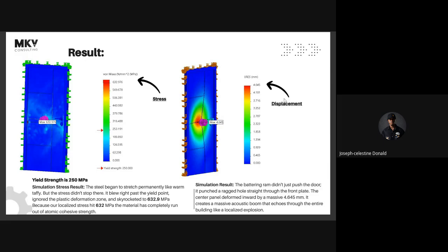The reason SolidWorks won't show you is that it cannot deform to infinity, it's just going to keep deforming. If you want to see it clearly, all you have to do is go to your deformation scale and, instead of true scale 1, just increase it to like 60. You want to see it 60 times normal. Understand? So you get this view of the full deformation itself.